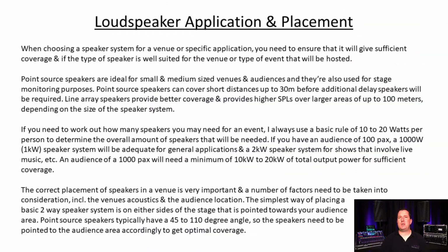When choosing a speaker system for a venue or a specific application, you need to ensure that it will give sufficient coverage and that the type of speaker is well suited for the venue or the type of event that will be hosted. Point source speakers are ideal for small and medium-sized venues and audiences, and they're also used for stage monitoring purposes. Point source speakers can cover short distances up to 30 meters before additional delay speakers will be